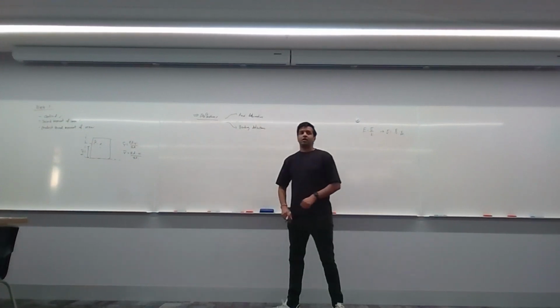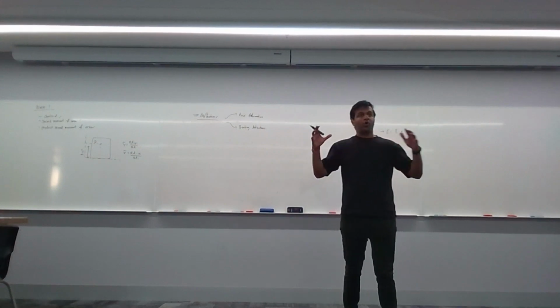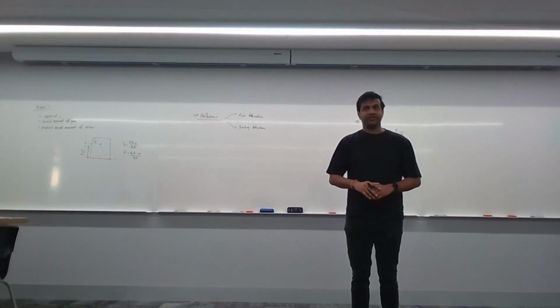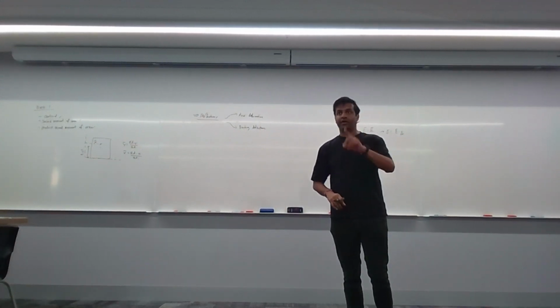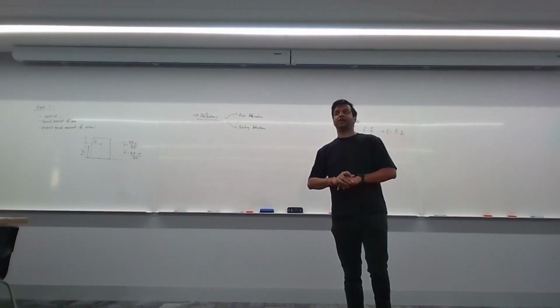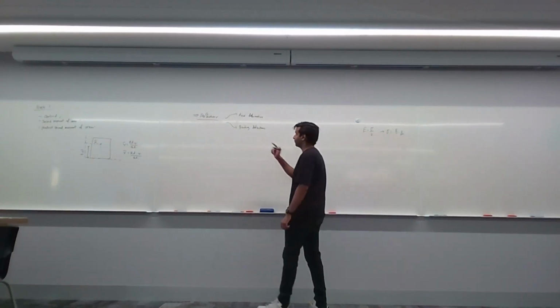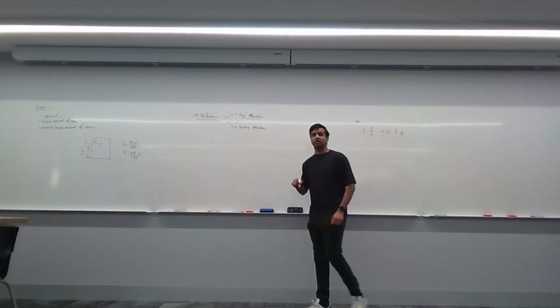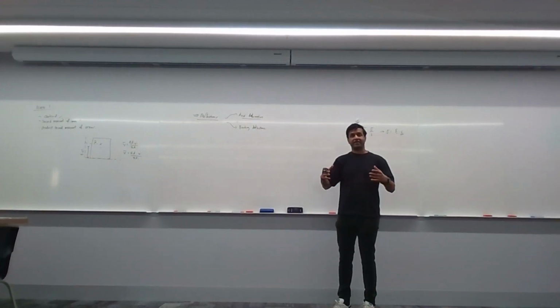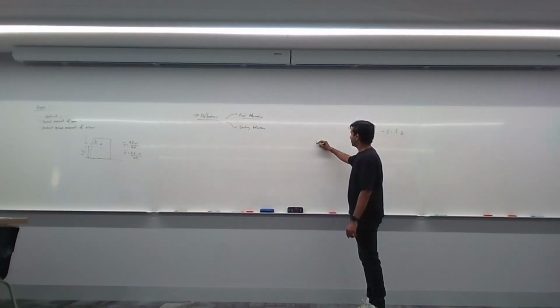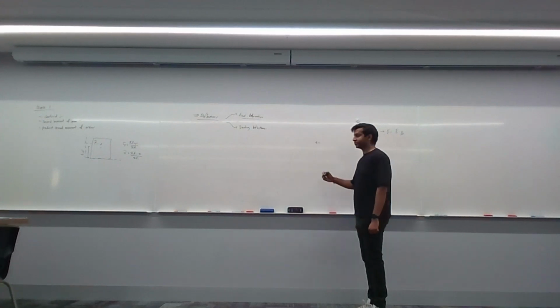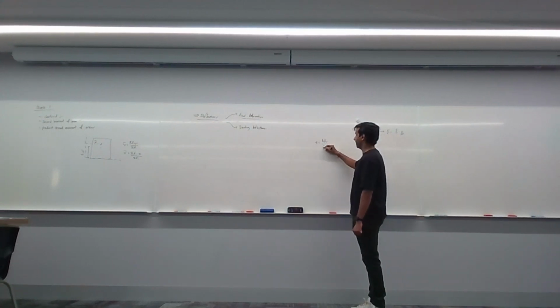Okay. Now I'm not gonna go through all of the details behind each of these topics, but there's a couple of things that I want to point out to you about each topic that you should pay special attention to. First thing is for axial deformations. We know that the formula for axial deformations is elongation equals to NL over EA.